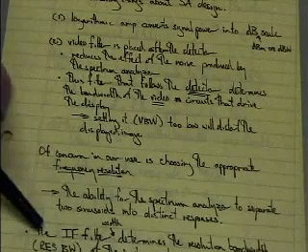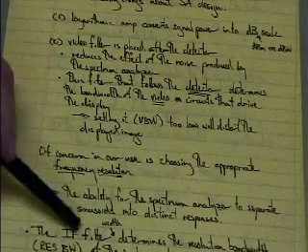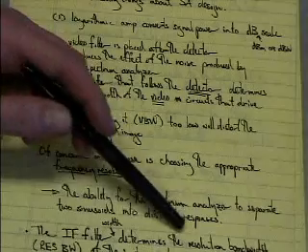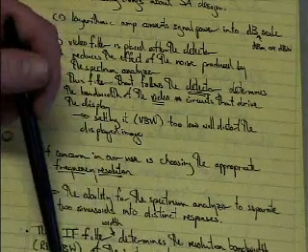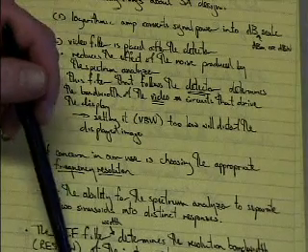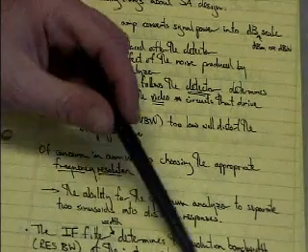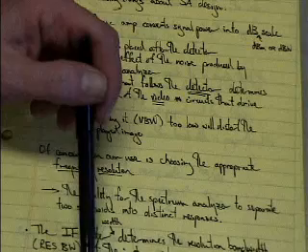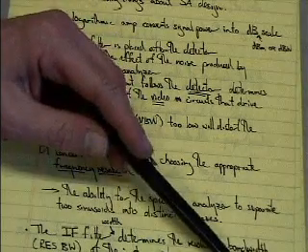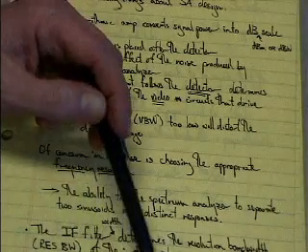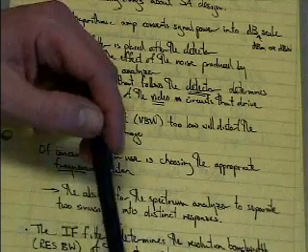So the IF filter width determines the resolution bandwidth, the res bandwidth, or the RBW of the instrument. This basically tells us how far apart two signals need to be in frequency in order to be identified as two unique sources. The width of the IF filter also determines the noise power in the system.